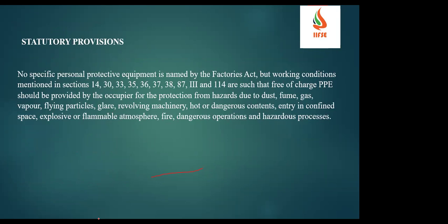If you see the statutory requirements, no specific personal protective equipment is named by the Factories Act, but the working conditions are mentioned in those sections, and the occupier should give PPEs without any charge. It should be provided with respect to hazards due to dust, fumes, gas, vapor, flying particles, glare, or revolving machinery, hot or dangerous contents, entry into confined spaces, explosive or flammable atmosphere, fire and dangerous operations, etc.